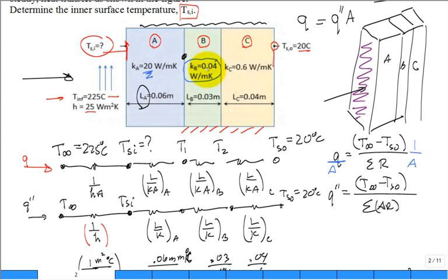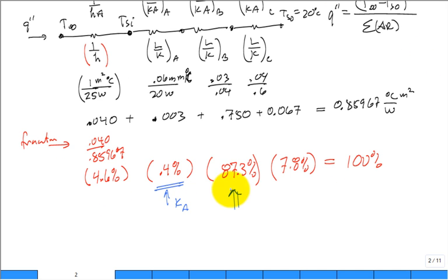It's very important. Look at the percent of the resistance controlled by it. So if you want to increase the resistance, decrease k of B, or if you want to do the other thing, either make it more thermally conductive or thermally resistive, you play with that parameter, k of B. All right, now let's finish up this problem.